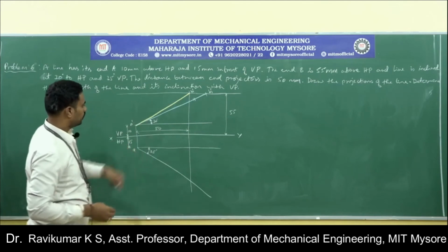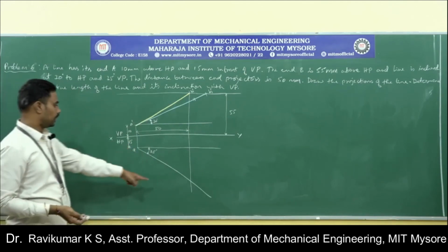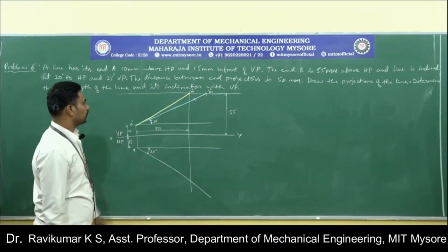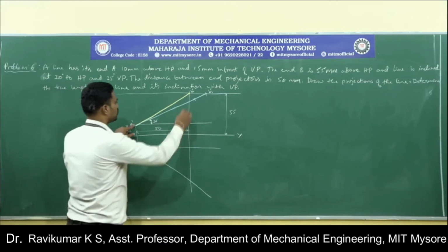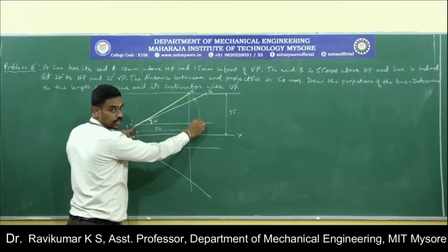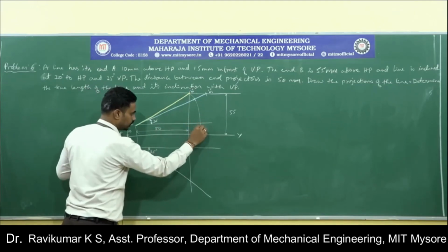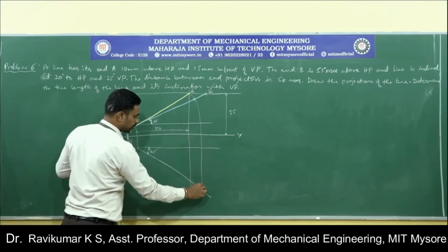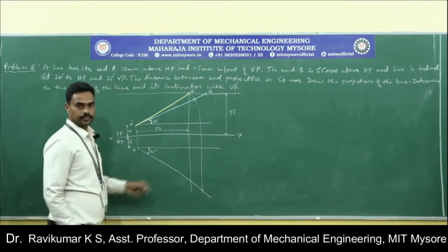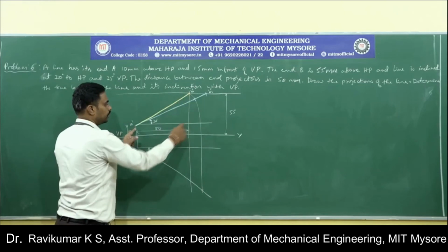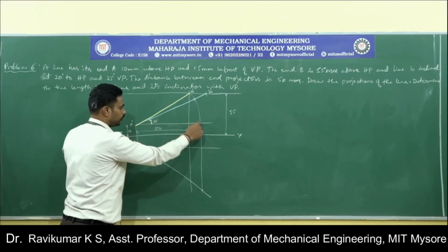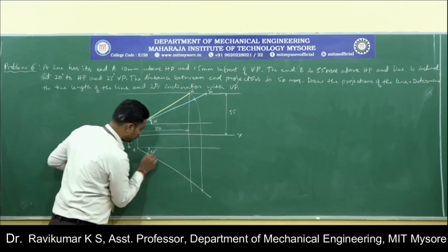Similarly, you need to get the true length and apparent length in the other view. Here you have got the apparent length, but here you have got the true length. You don't know the distance, so you just rotate this A dash, B dash. Rotate this and make it parallel, and from here drop a perpendicular. Wherever this perpendicular cuts this line, that should be the true length, because you have rotated this one. Here it is appearing parallel, this A dash and this point appear parallel in this view. Therefore you will get the true length in the other view. So this should be the true length.